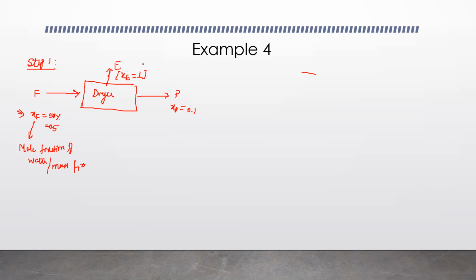Remember, don't get confused between evaporation and drying. In evaporation, your abundant component is liquid. In drying, your abundant component is solid. All right. So once we have this with us, we can simply form different equations for material balance and solve the problem. But as I told you, I'll tell you a trick to deal with drying problems easily.